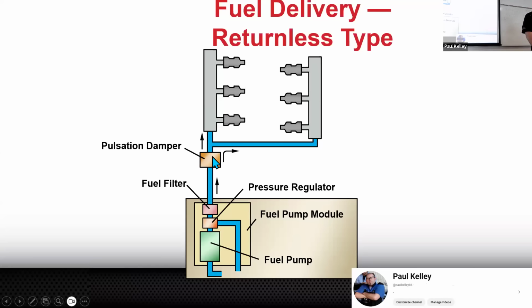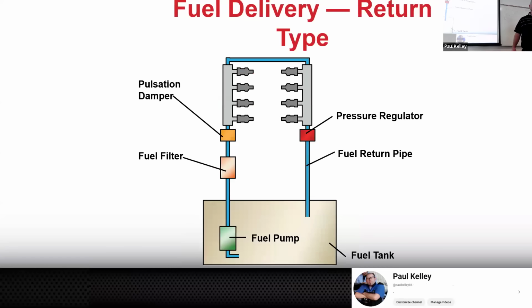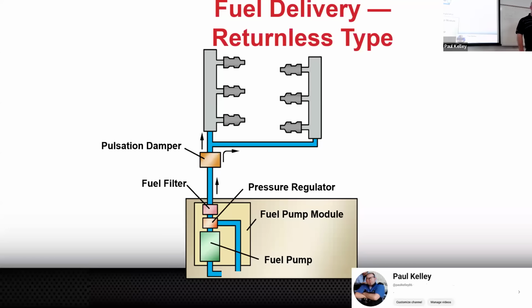By the time it hits that pressure line, it's already regulated, and it goes to the rail, and it's just going to be chilling at the rail. The rail only gets 50 PSI because the regulator was down in the pump, and it only allowed 50 PSI. In a diesel, they'd call it common rail, right? This is not really complex to me. I thought this was simple. I've seen on the ASE on a number of occasions where it'll say a returnless fuel system, and people are like, oh, what? It's like, yeah, this is pretty much what everything's had for like 20 years. This is the norm. This is actually a little bit more rare to see because it's old school. This is new school. No biggie.